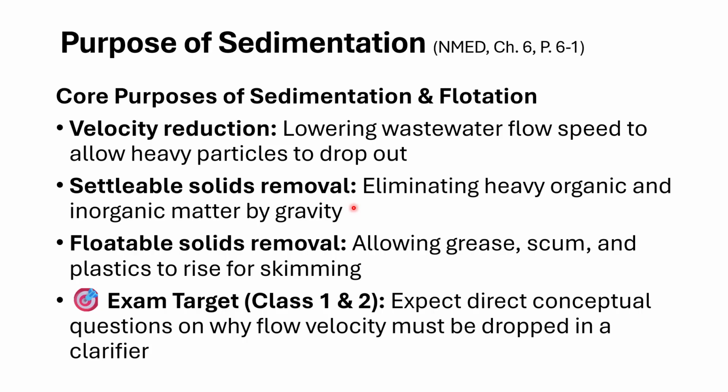That's detention time. Okay, so in addition to letting gravity take care of those settleable solids, that heavier organic and inorganic material, which settle to the sludge blanket, the organics, the fats, oils, greases, the lighter stuff with a specific gravity less than 1, lighter than water, is going to rise to the surface, and we're going to skim that off.